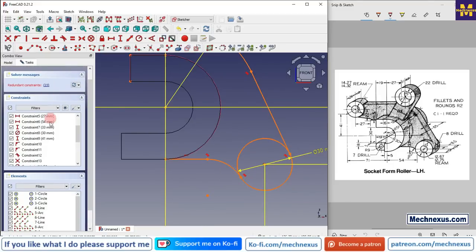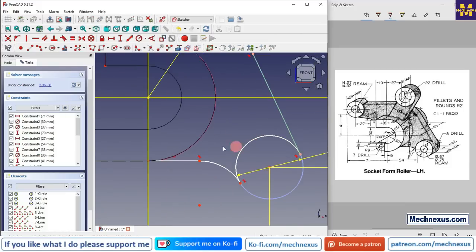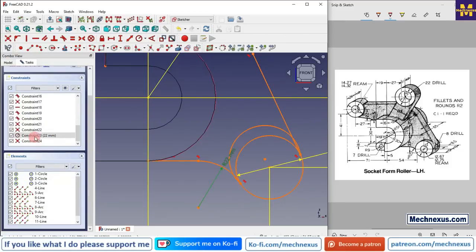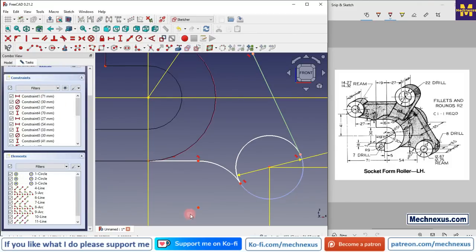And now we will select a 3-point arc and create an arc equal to our construction one. So now here we have the conflict, so we will select it, delete it or deactivate it. So we will simply delete it, and this is the radius of R22, so we will select it and provide the radius of R22. And now here we will select this and click on the merge, and here we will delete the constraint, and we will also delete it.